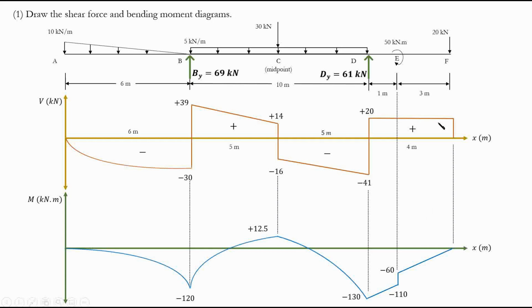Now let's say again, at the right you have a fixed support. At the right you have a concentrated moment. Again, at the end, let's say we end up with like negative 20, and of course at the end we will have a clockwise moment, right? At the end again, my point is just we end up with 0. That's how you check. So at the end your line goes to 0. Doesn't matter if it's vertical, horizontal, linear, parabolic, it just gets to 0. It starts with 0 and gets to 0, right?